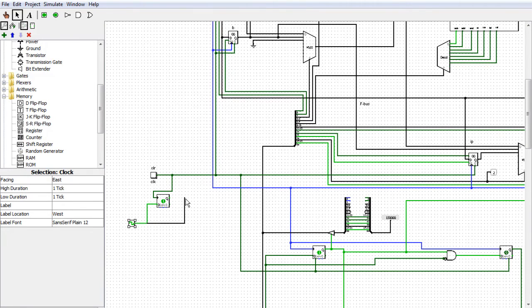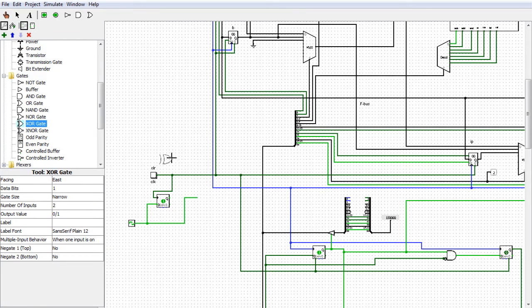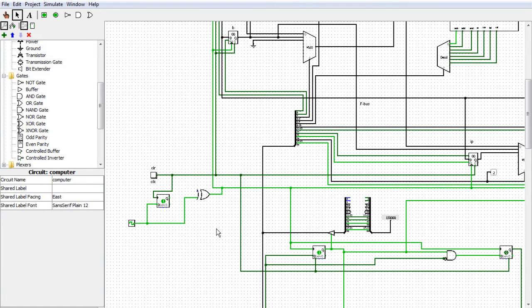And then this is going to also drive the clock signal. But what we want is to invert this if we need to invert it. So inverting is generally done with what gate? The exclusive OR gate, or XOR, or its negative. And we'll just pipe that into there. All right, so let's just try this. And we see that if this starts high, this is going to be low.